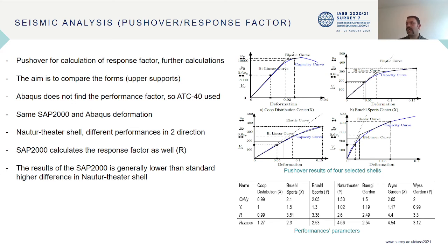These are really precise and fitted by MATLAB very well. We have those curvatures and the results of the pushover. The main result is the response factor, which can later be used by other designers to reanalyze those shells and rebuild them based on their local criteria and their specific country's seismic standard.